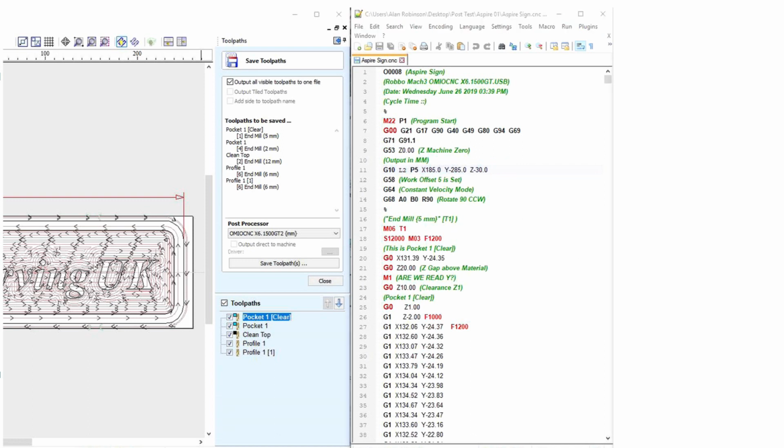G10 tool offset and work offset tables. To set the offset values of a tool, program to set the coordinate values for the origin of a fixture coordinate system, program G10 L2 P X Y Z A B C, where the P number must evaluate to an integer in the range 1 to 255, the fixture number, values 1 to 6 corresponding to G54 to G59, and all axis words are optional.